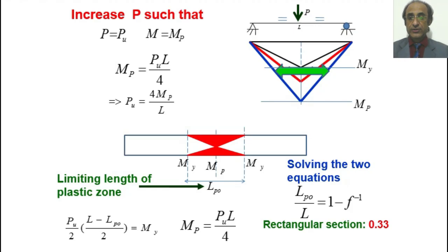The adjoining regions are also part of it, though they don't fully contribute. At one particular point we have a fully plastic section, but it's not the case in the regions to the left and to the right. They try to resist the plastification process because they still have moment capacity. So we'll see how a plastic hinge actually looks.